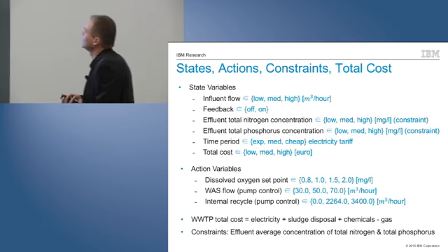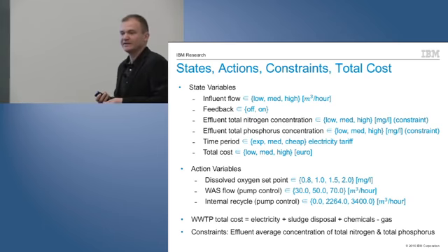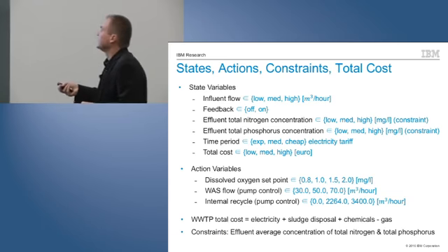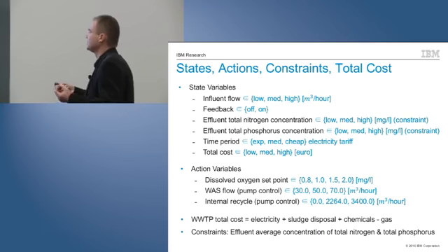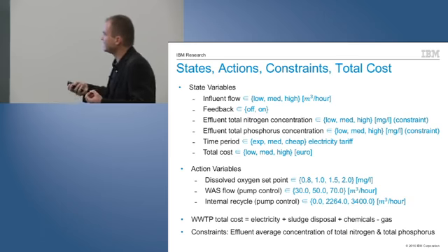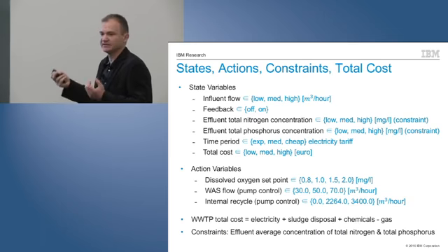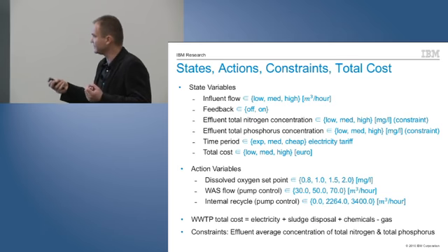And if you take a look at influent flow a day after Christmas, the volume is huge and the treatment is very expensive. Feedback must be inside, not because the volume is high, it is not, but because the chemical concentration in the feedback is very, very high, something like 10 times higher than at influent. Feedback can change the chemistry of the water significantly.